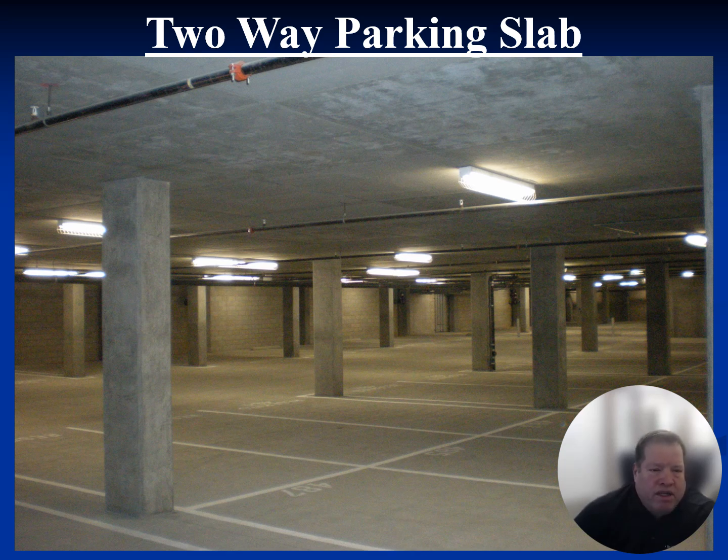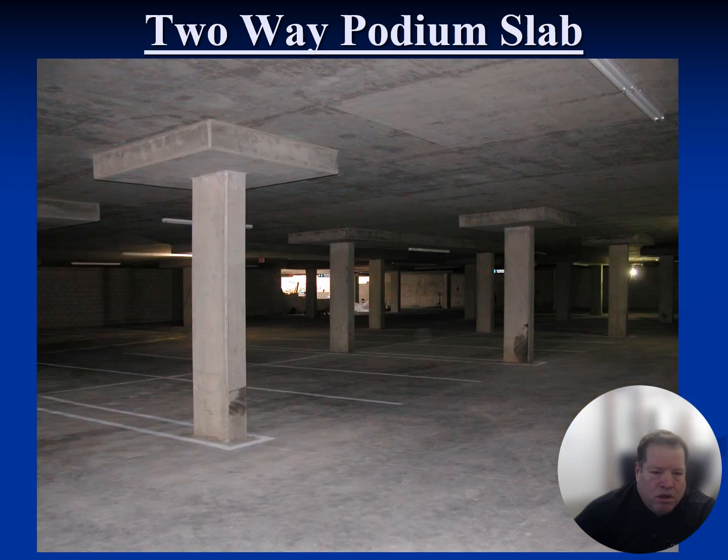And for relatively light loads with parking, hotel, apartment, office, stud rails are great. When you start getting into the larger loaded structures, we typically go for a cap, which you can see right here at all these columns. Same general column size, again for primarily axial load with some minimal moment.